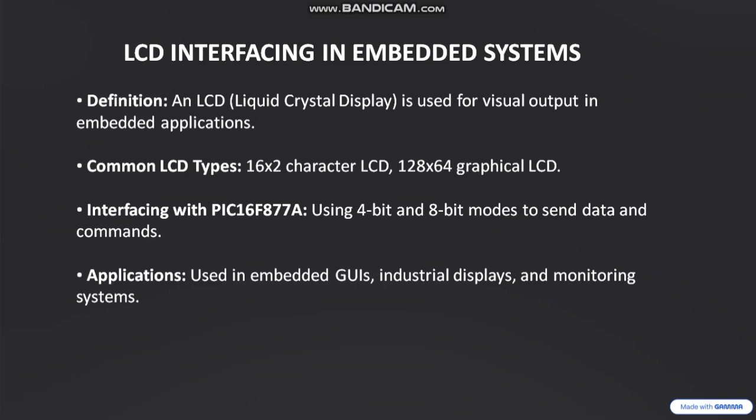The next one is LCD interfacing in embedded systems. An LCD is used to display output information to the users. The most commonly used LCD is 16x2. It can be connected using 4-bit or 8-bit mode. In my project, I used 8-bit mode. The microcontroller sends commands and data to the LCD. LCDs are used in devices like digital clocks, calculators and industrial panels.